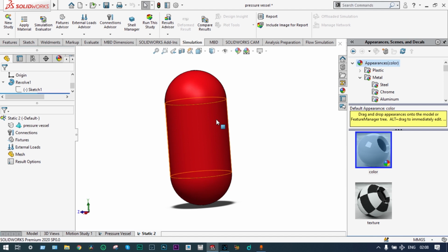Now sometimes it may so happen that if the size of the model is very big, we cannot go for further meshing. That means the software has some limitations. To avoid this, if the model is symmetric, we can break the model into simplest forms and go for analysis using symmetric boundary conditions. That we will follow here because this model is symmetric definitely. So we will try to divide the object into different pieces, and for each case we'll find the stresses and compare with the previous cases.